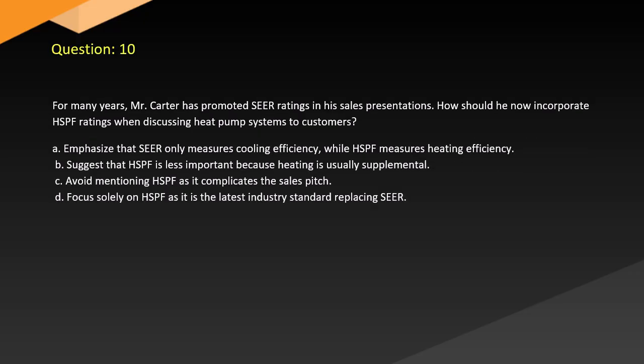Question 10. For many years, Mr. Carter has promoted SEER ratings in his sales presentations. How should he now incorporate HSPF ratings when discussing heat pump systems to customers? A. Emphasize that SEER only measures cooling efficiency, whereas HSPF measures heating efficiency. B. Suggest that HSPF is less important because heating is usually supplemental. C. Avoid mentioning HSPF as it complicates the sales pitch. D. Focus solely on HSPF as it is the latest industry standard replacing SEER.